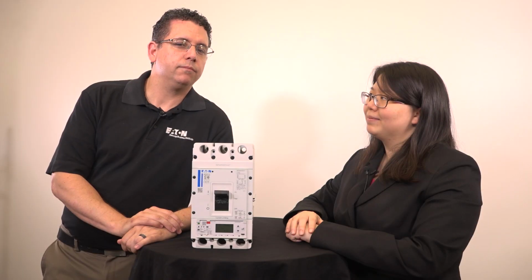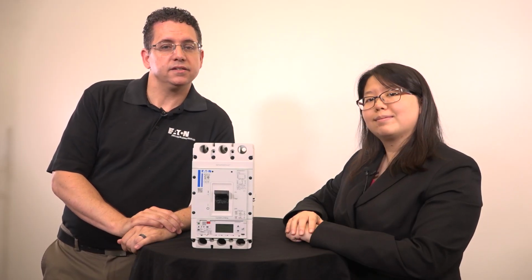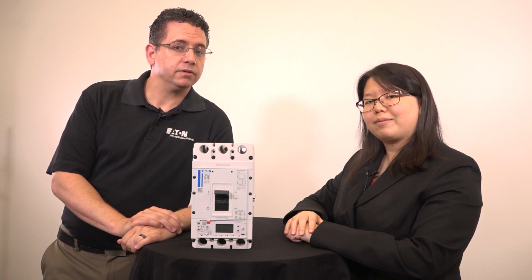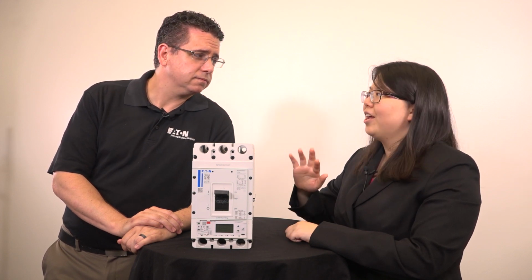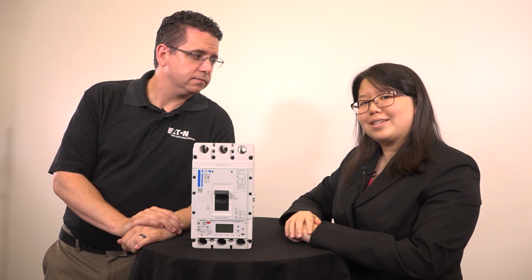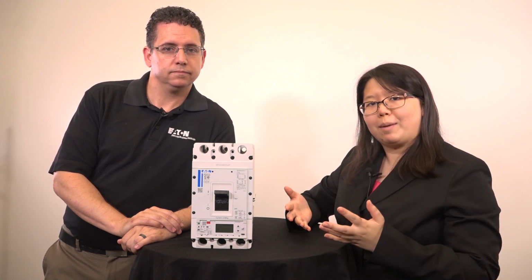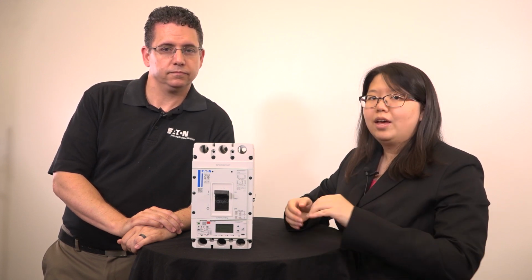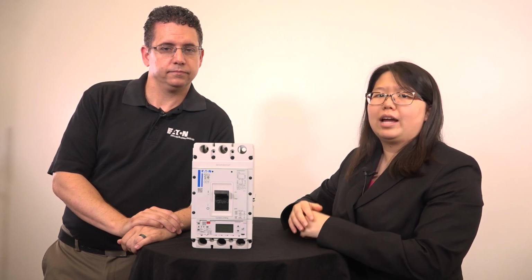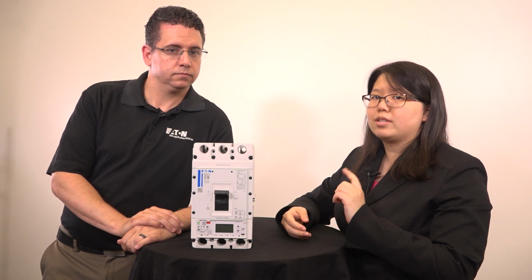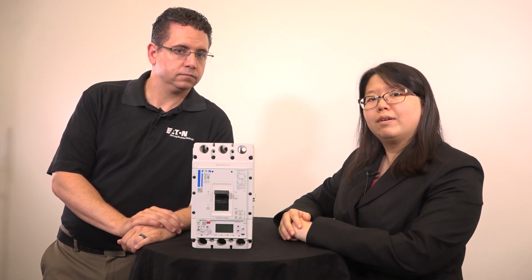So, if I had a breaker for 10 years, and it says it's got 50% life remaining, does that mean it's going to last for 10 more years? Not quite. Breaker health is calculated as a function of all of these parameters, not just runtime. Your health may have been impacted because of a high number of short-circuit trips or a high number of operations, or perhaps it was just a single high-current fault trip.